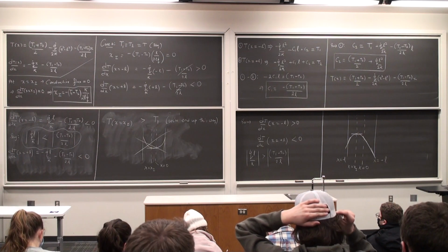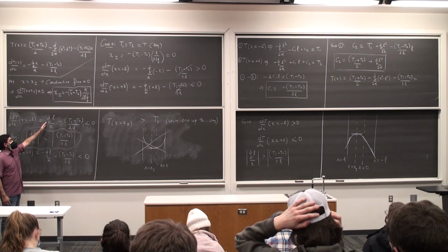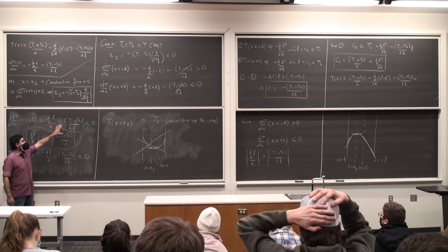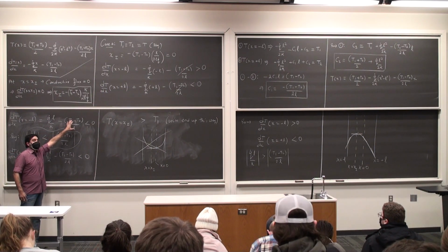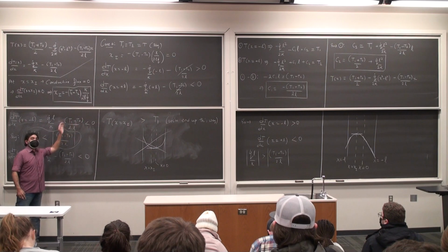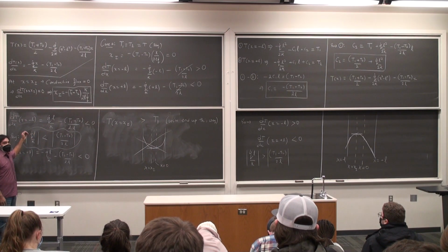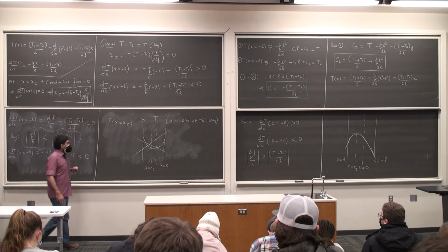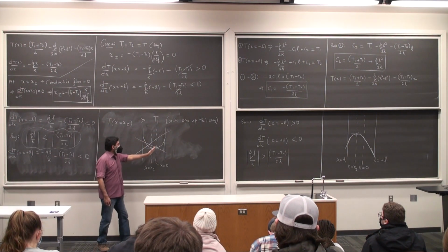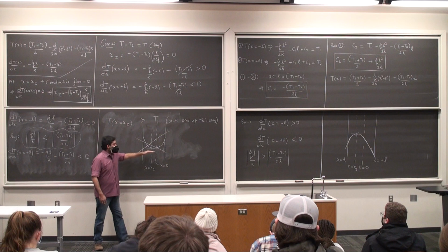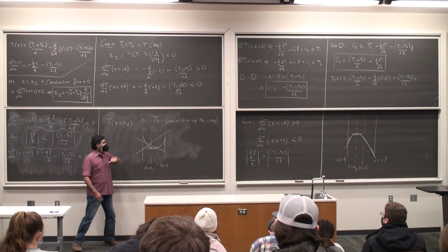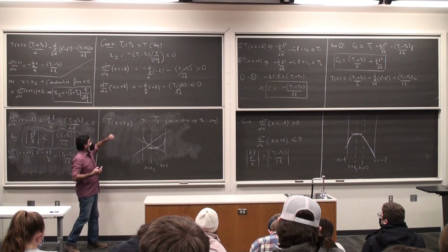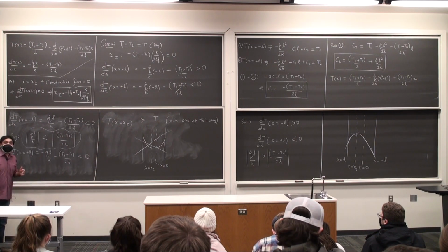Okay? All I'm saying is that if I'm looking at this situation here, I have two choices. Depending on the magnitude of this quantity versus the magnitude of that quantity, this slope can either be less than 0 or greater than 0. If this is less than 0, I end up with a very sad situation here, where I have heat entering in, and essentially the temperature there, I have found out, and you'll see the math, is greater than T1, so that cannot be the case.